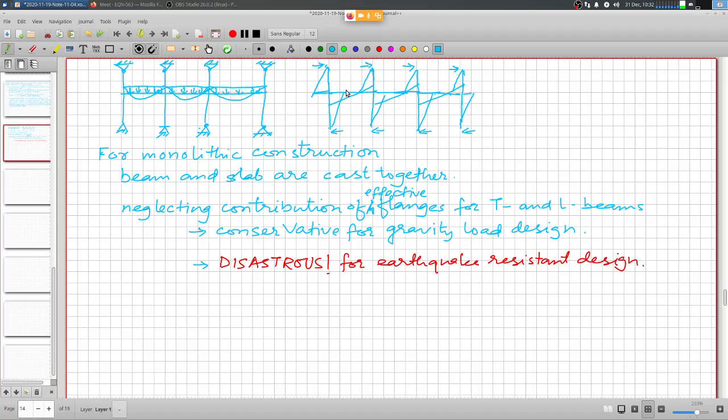So hardly there is any concern of plastic hinges developing in the mid span. The beam sway mechanism should aim at plastic hinges near the column face. That is where the maximum moment happens, and because it is a reversible moment, the signs can go back, positive, negative.